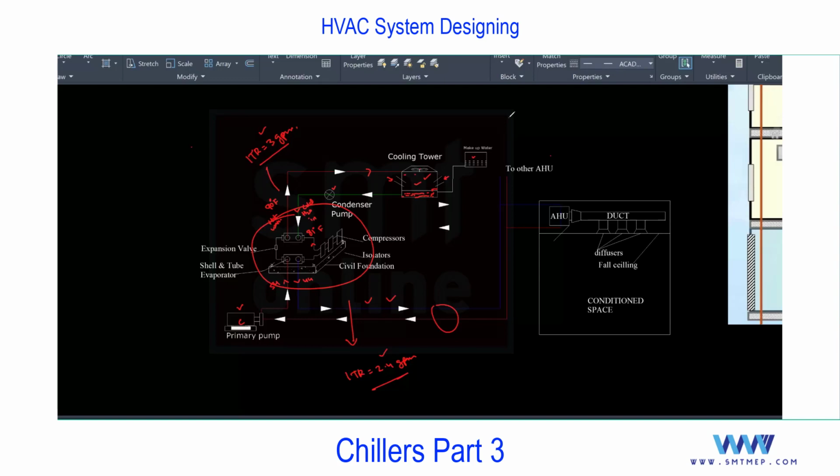For example, compare this chiller, for big project, if you use DX system, you need to supply the refrigerant for the entire FCU and AHU. And compressing that much of refrigerant requires very high capacity compressor, compared with circulation of water.